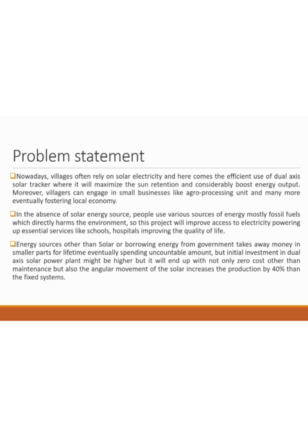But things in solar energy do not work like that. It is just an initial investment to fix a solar power plant, and then there is just maintenance that we have to take up after 3 or 4 months. Instead of fixed solar panels, using dual axis sun tracking solar panels increases the production of electricity by 40 to 45%. Eventually, more electricity is produced at lesser cost.